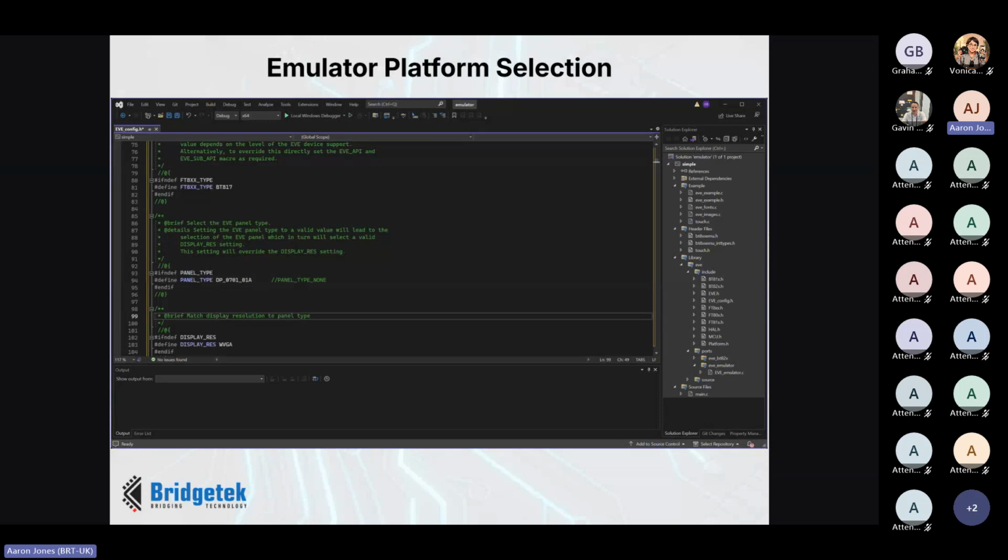Therefore, you can easily set the emulator up for your own display panel and Eve hardware by setting the values here. If your project uses Flash on the BT81X series or BT820, you can also use that too by specifying the path to your bin file, and likewise the SD card for the BT820. And so you can emulate projects which store assets in the Flash or SD card.